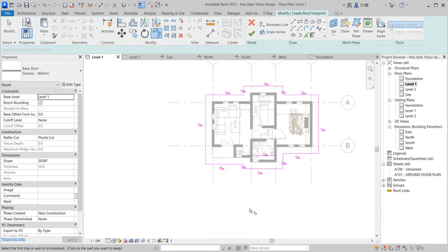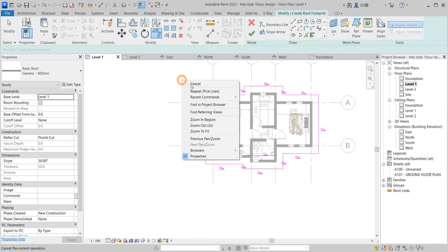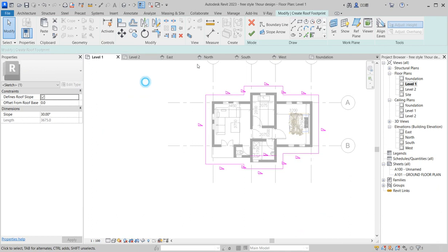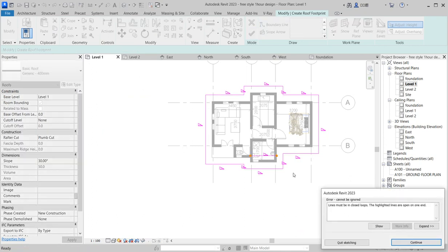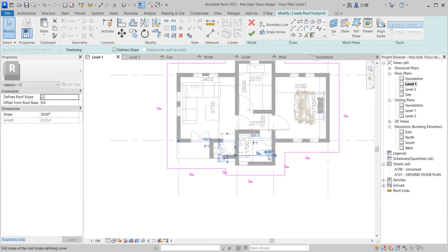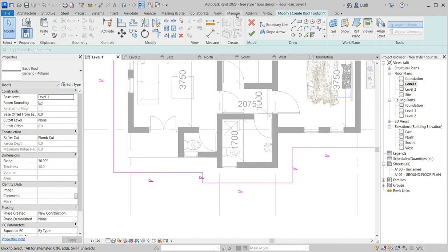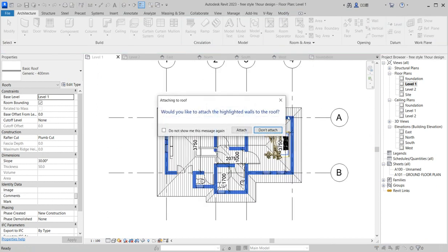Fine. So we select this and we get what we want. Is this the slope of the height we need? What is it? That's 30. So you click finish. Something is lying within. So that's the thing about Revit. It's going to tell you that those things are not working because you cannot have a line inside a line when you are in sketch mode.